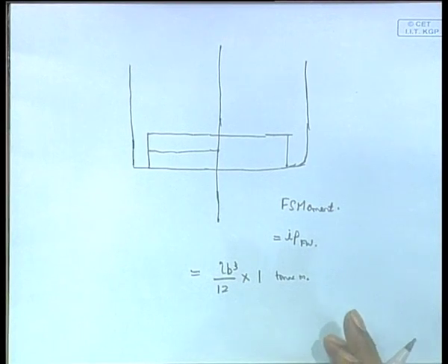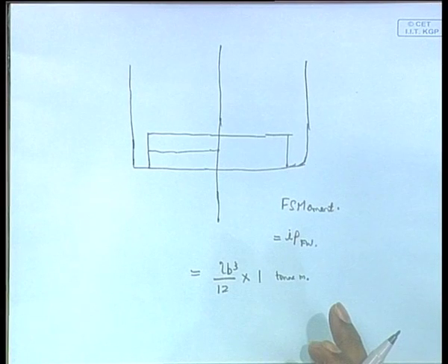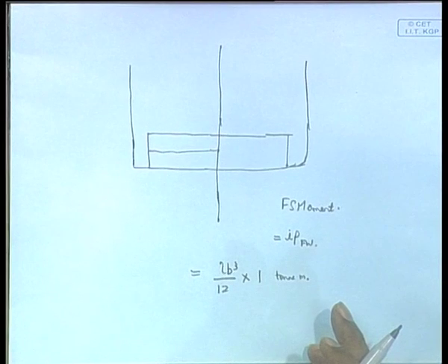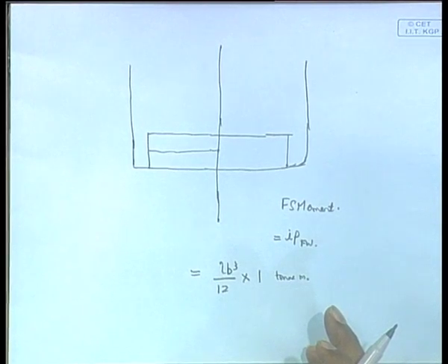So initial G0 G1 is, theta is said to be 3 degrees, it is listed 3 degrees to port. So tan 3 degrees into GM. Is GM given? KG and KM are given, right, so you can find GM. So G0 G1 you find, that is your initial G0 G1. You should have got it as tan 3 times GM, that is 0.054.